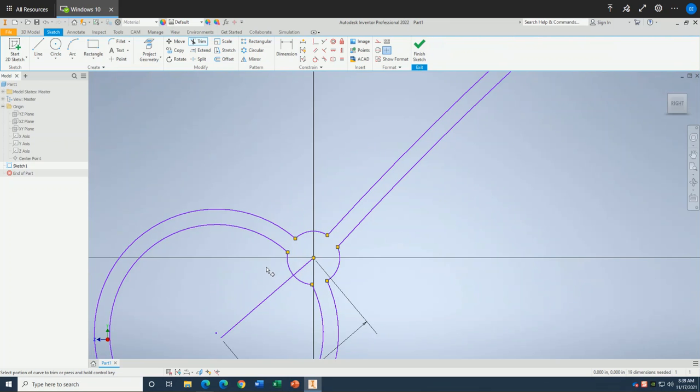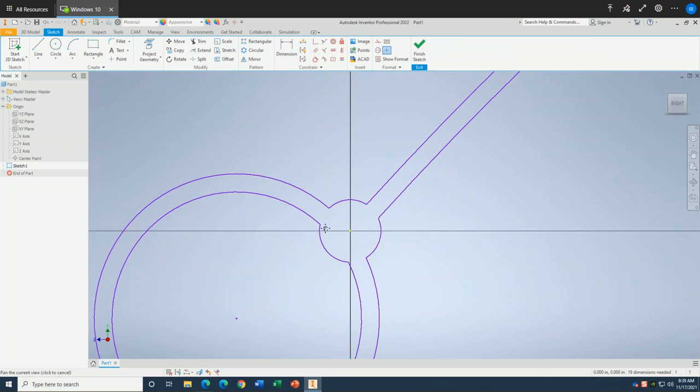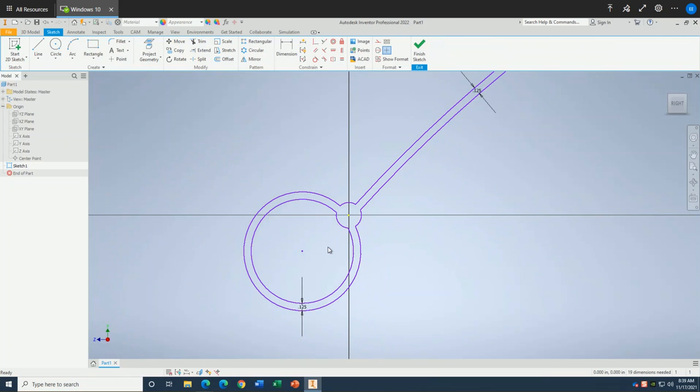You probably already understood that I'm going to extrude everything at the end. There will be two extrusions, one for the axle and one for the arm, the second arm. So for the axle, I decided to have it be 1/8 of an inch, the OD, or outside diameter. So I'm going to draw that about 1/8 of an inch, or 0.125. So 1/8, enter.